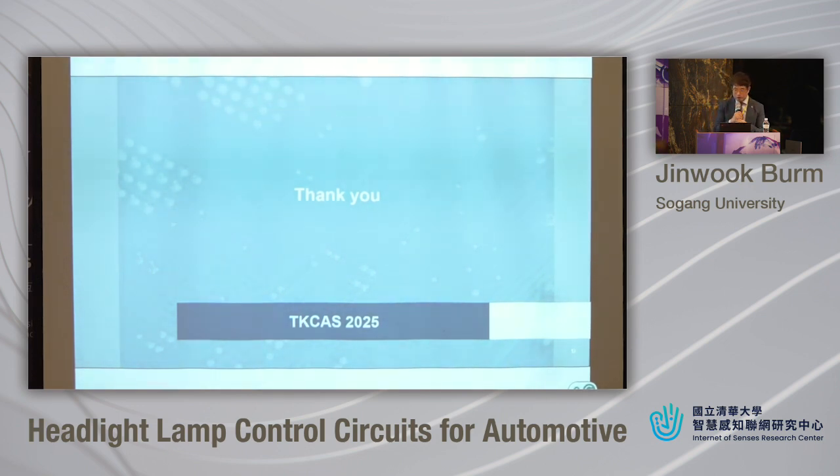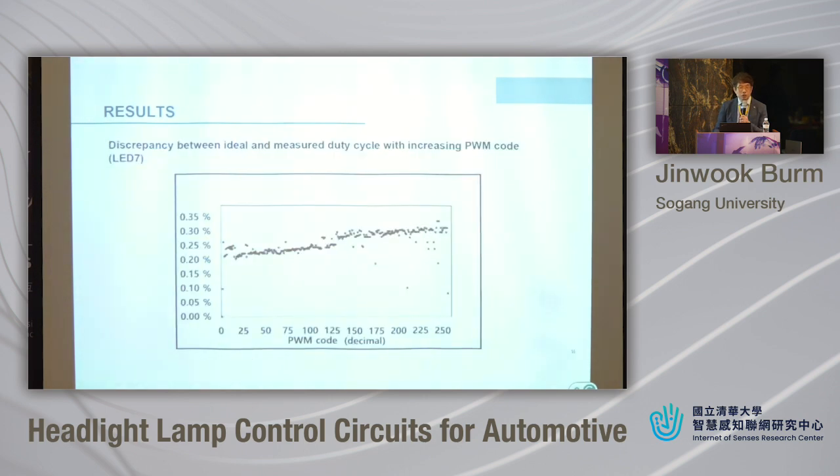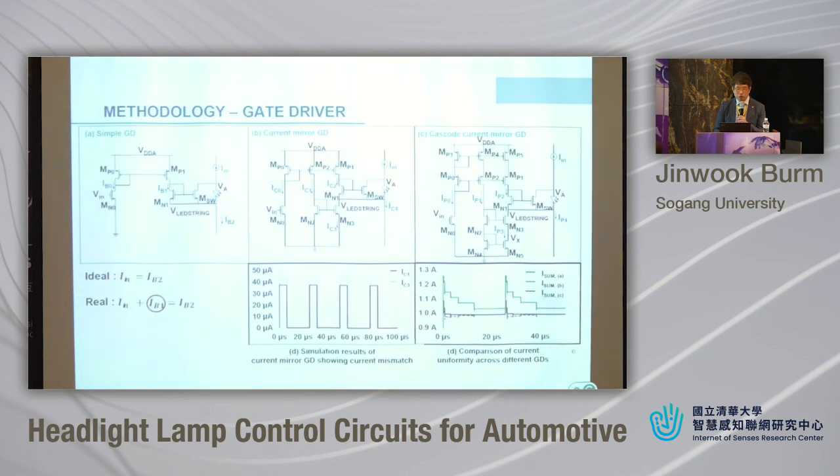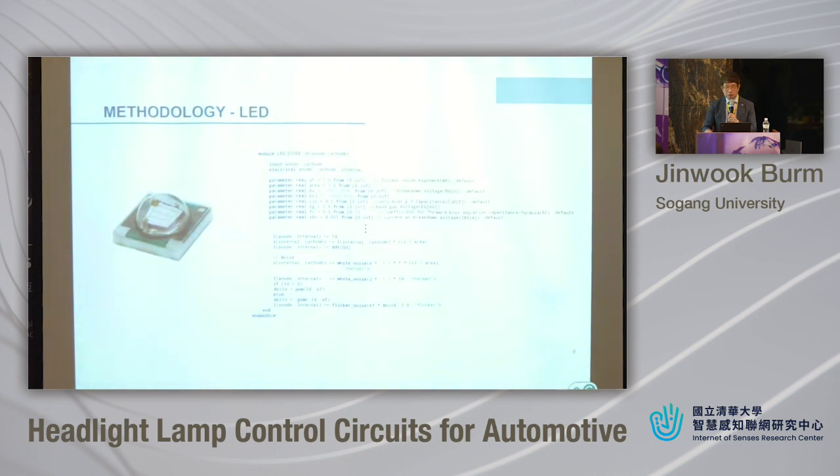Okay, so you are asking about the Verilog-A modeling for the LED. During the simulation steps, the LED is very difficult to model, and we realized that using Verilog-A, we can express all these different components very precisely. The level we can achieve depends on the models, but our model is not very complicated, just a resistor with some tunnel voltage. And we can add some noise models onto it. So we think this is quite accurate to model the LED behavior. If you would like to do more, we can also make the models more involved, and depending on how you would like to model the LED, different levels of accuracy are possible.